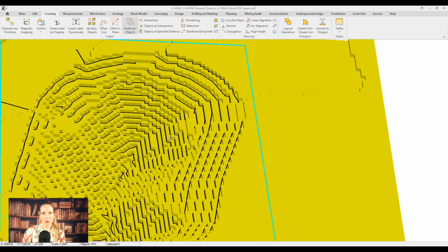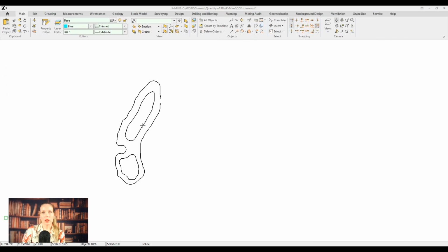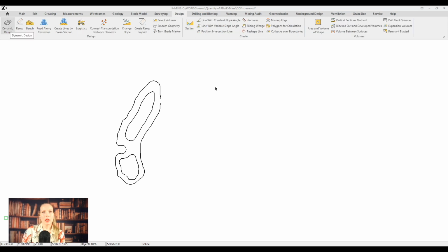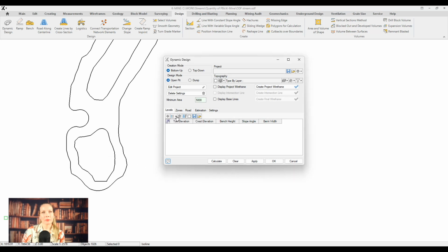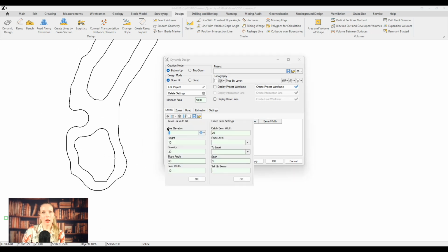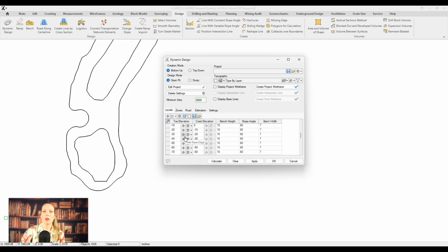First, draw a contour where you want to get isolines aligned with the level list. Use the create iso objects command to generate the isolines you need. Then pick out the lines you want to work with. Further, in our case, it should be lower and unique, not repeating the previous elevation. Smooth them out for easier work, and then we move to the fun part.